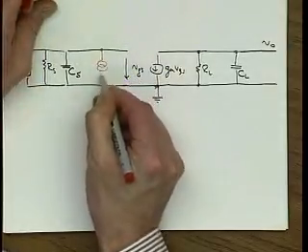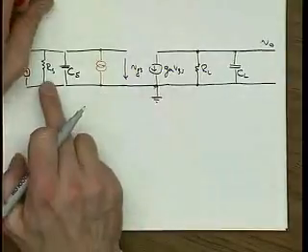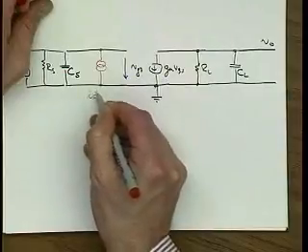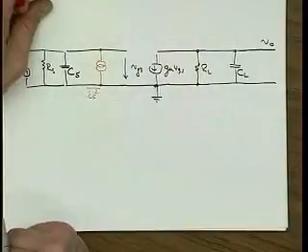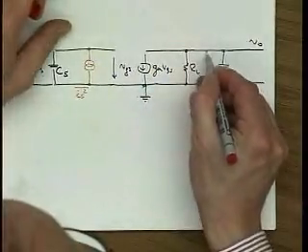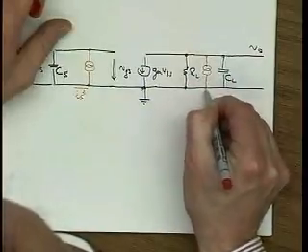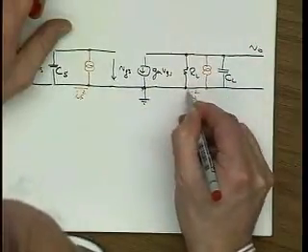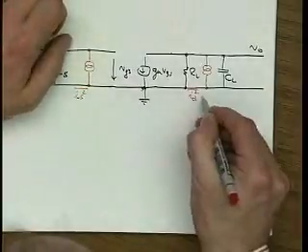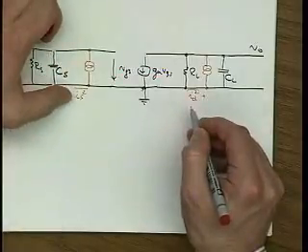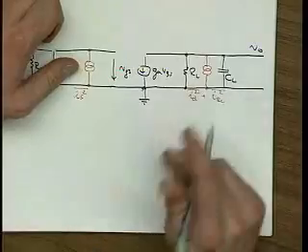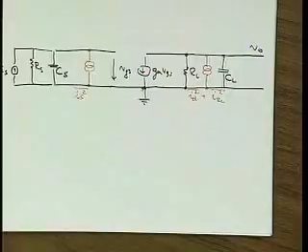So then there are the noise sources. First we have here a resistor that contributes noise IS square at 4 kT over RS times delta F. Then here we have two noise sources: ID square, 4 kT 2/3 GM times delta F, plus, did I say RS? It's 1/RS, right? Plus IRL square, 4 kT 1/RL times delta F. Okay, so these are our noise sources.